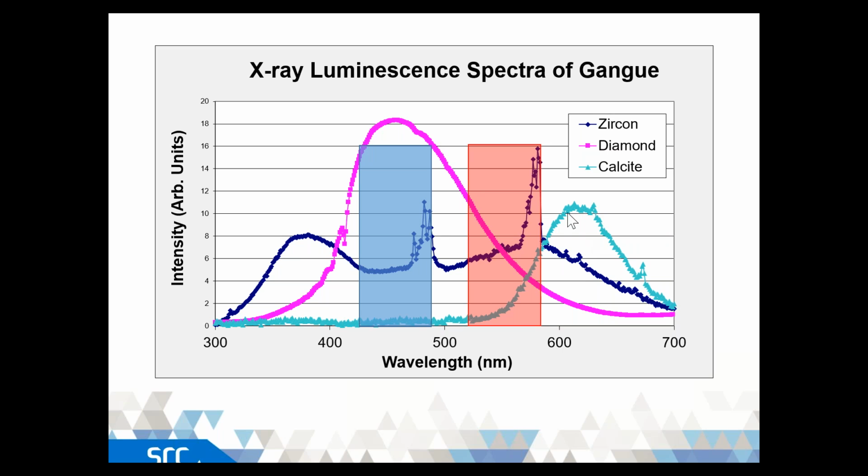And so if you have a deposit that has a lot of calcite or some veining or a system within that kimberlite, it can then present a problem in your downstream recovery and increase your yields with the material that's going to the final sorting. So to help alleviate that, you can add filters.